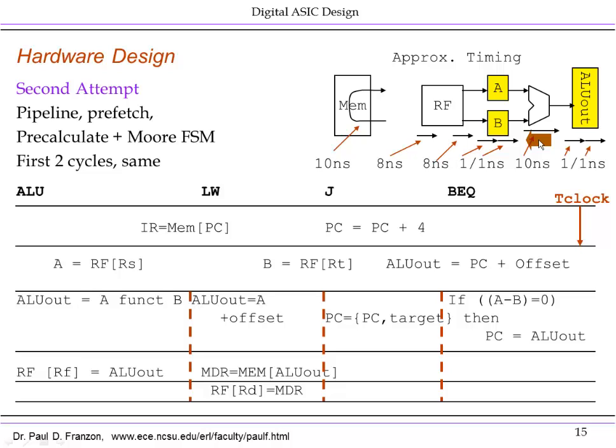Again, the key here is we took a complex micro-operation that was very slow, broke it into much faster micro-operations by adding registers, and then calculated our performance to see if it was going to be better. And again, this is the type of thing you can do in any hardware design to explore the different options to implementing your algorithmic intent on alternative possible data paths.